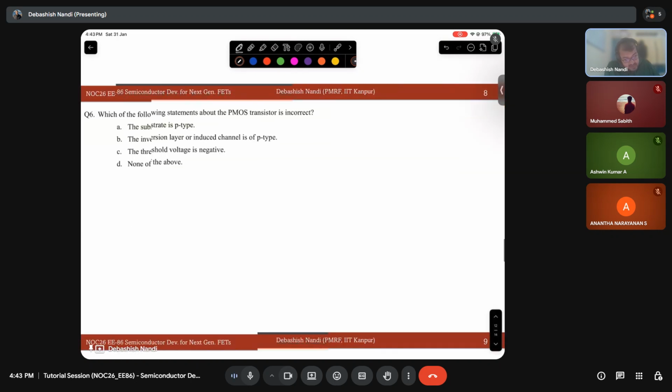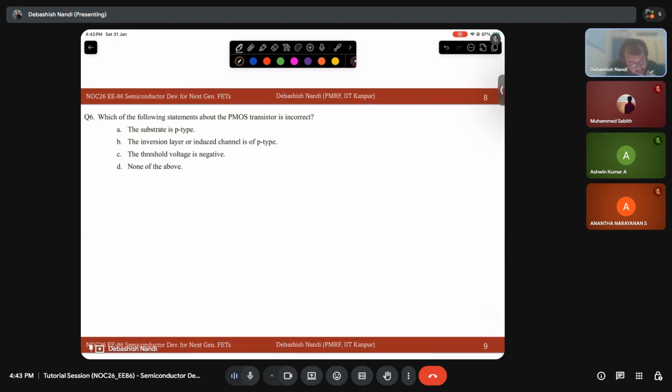Then next question is, which of the following statement about the PMOS transistor is incorrect? Threshold voltage is negative, generally true. So PMOS transistor means, what will be the doping of the source and drain?